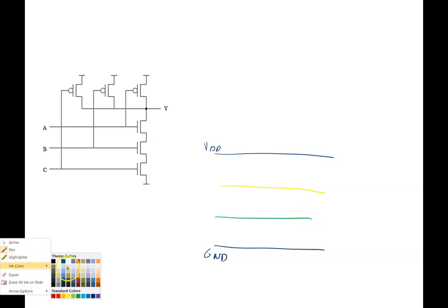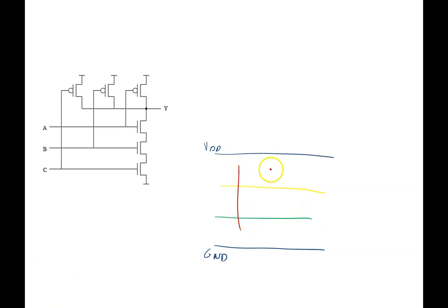And I can just do that at the very beginning. And I can just get rid of the series part. So I got the NMOS side looking like this. And I can just tie this to ground, and these are in series, and then drain just taken to the output. So that's my output. Now we start with the source again, and I call it drain, so I'm gonna put these 2 in parallel.